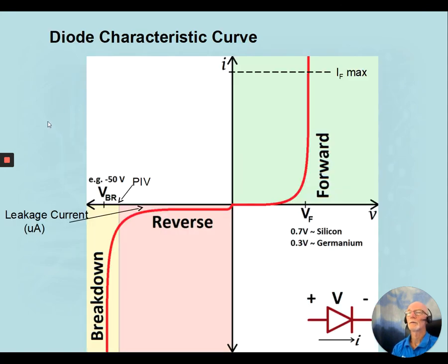However, first of all, we want to look at what's called the diode characteristic, or the current characteristic curve of a diode. If we forward bias a diode and start increasing the forward voltage from 0, no current will flow until current starts to flow a little bit, and then all of a sudden we get what appears to be no restriction in our current flow. And for a silicon diode, this happens at around about 0.7 of a volt, normally somewhere between 0.6 and 0.7 it starts turning on, and at about 0.7 it's fully turned on.